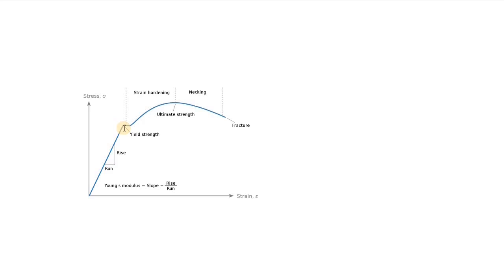Now, why do they do this? They do this because they know that if they design the structure from this point to the yield point, although this is not the final capacity of the building, the building still has some strength left to resist the applied load.